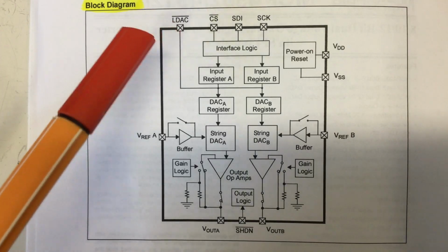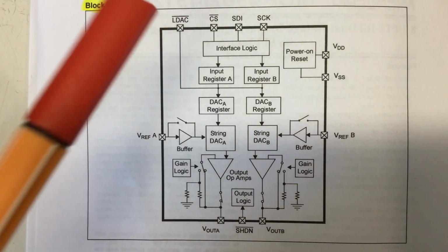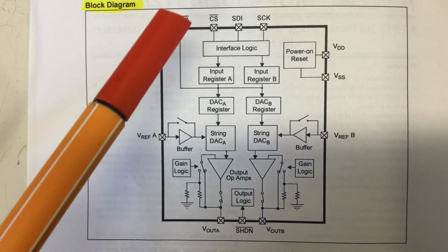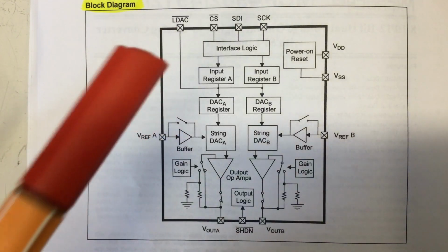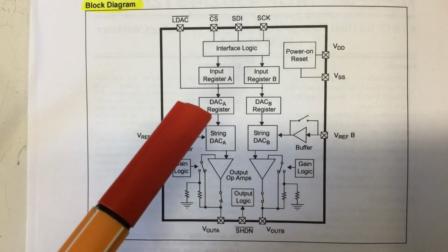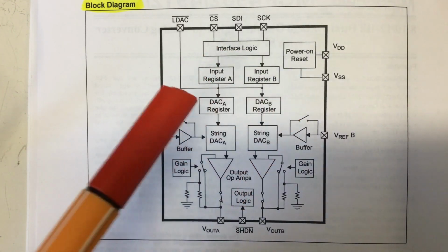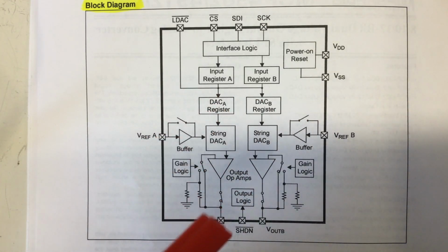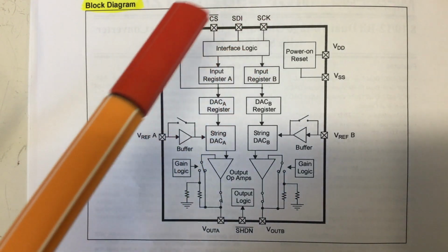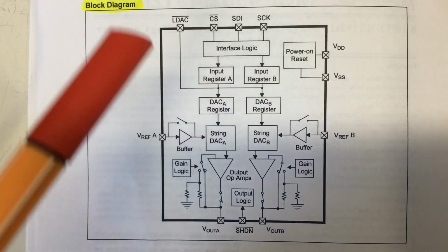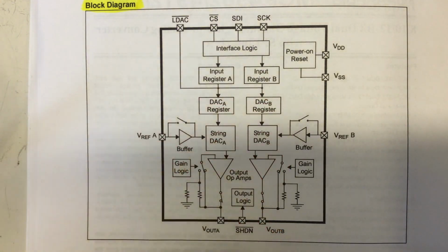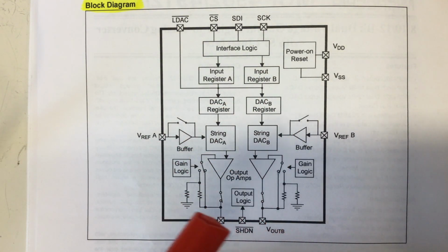And that's where the LDAC pin of the MCP48s and 49s comes in, which I ignored so far. Up to now, we have that constantly pulled low, meaning whenever we load a value via SPI for one of the registers, it directly ended up in the DAC registers and immediately changed our output voltage. But if we keep it high while we are loading new values for both channels and then pull it low, we can synchronize the value changes of both outputs.